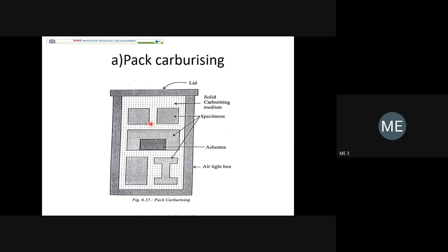After surface heat treatment, the inside part of the specimen remains at 0.4% carbon. Only the surface part of the component is hardened; in a later stage, we will discuss the hardness. The percentage of carbon increases from 0.4% to 0.8% by diffusing carbon atoms from the carbonaceous gases at very high temperature, again above the austenitizing temperature.